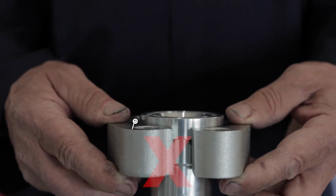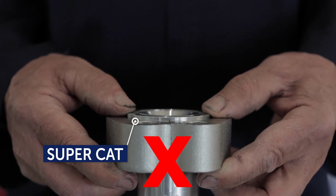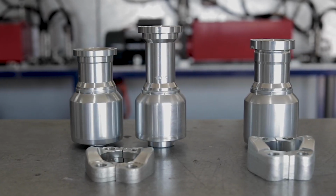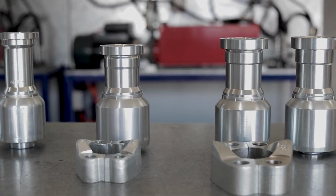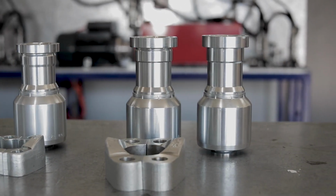So again, while there is only a small difference in these two flange sizes, the flange clamps are not interchangeable. In short, many flanges may look identical, but that is not the case, and mixing components can lead to system failure, severe injury, or even death and destruction of property.